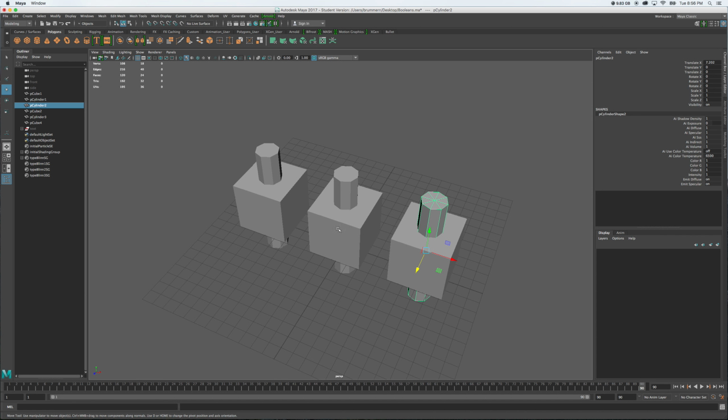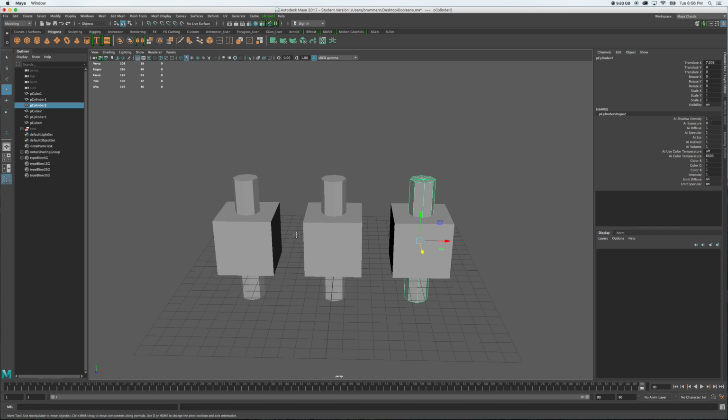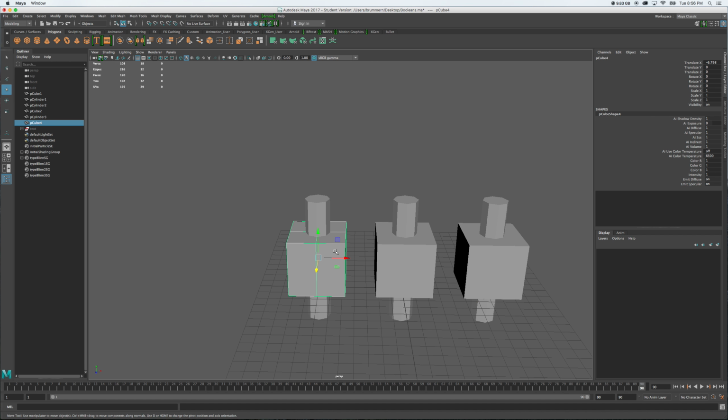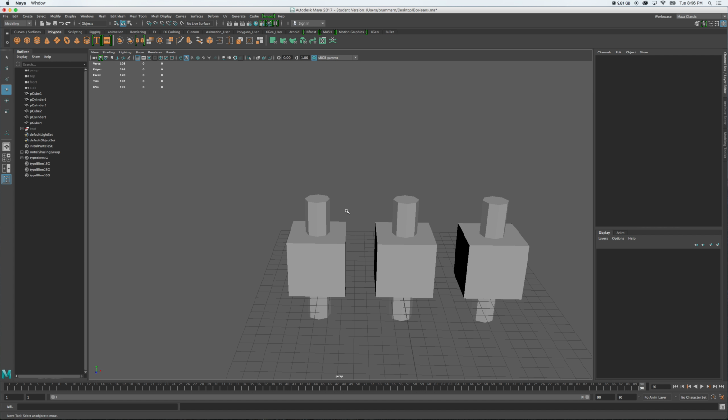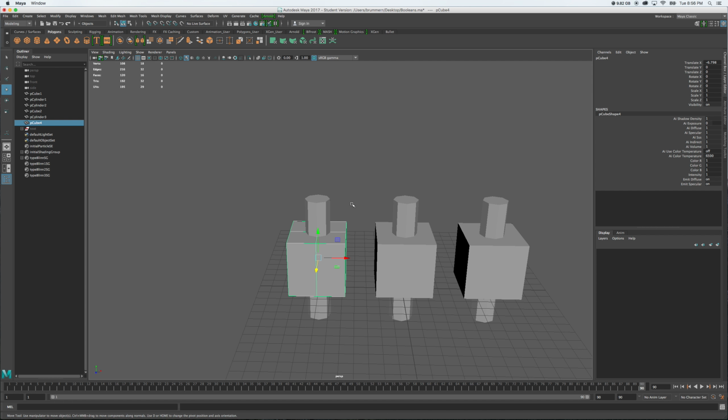So we'll just go right down the list. We'll start on the left-hand side with our union operation. The key to making any of your Boolean operations function properly is essentially just order of selection. You need to pick the object that you're going to be removing or adding to first, so the main object. And then you're going to pick, with shift held down, you're going to left click and select the object that will be used as the tool to do the removing or adding to.